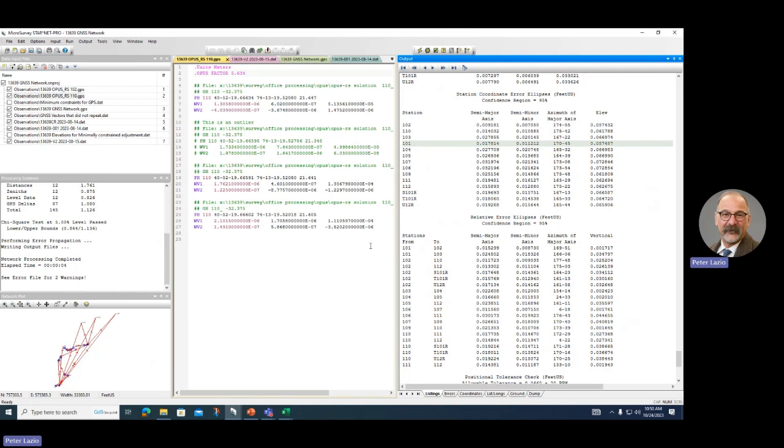But then I'm going through and it's affecting the chi-squared, and I was getting to where that was basically failing. So then I had to go back in and tweak the actual adjustment to get those error ellipses down. And I'm like, it doesn't make sense to be so focused on this. I feel like that's just creating a worse coordinate for the PSM. And you're right, you're manipulating your data in order to get an artificial result.